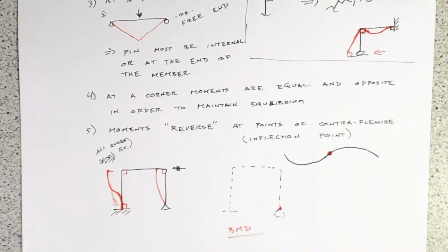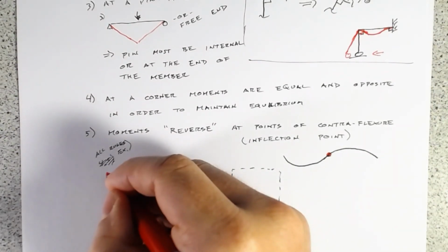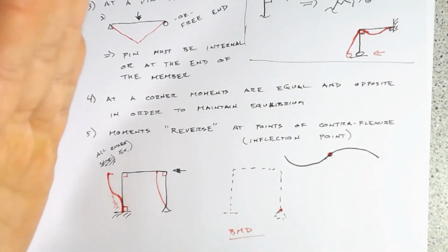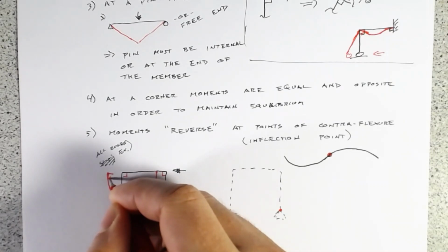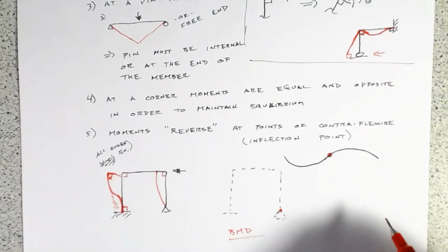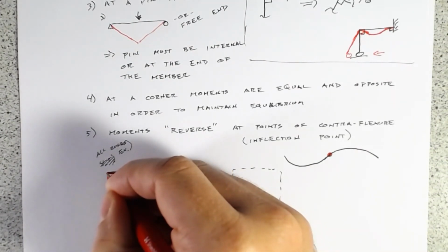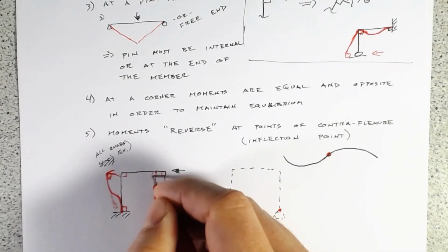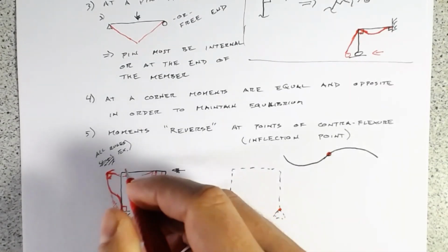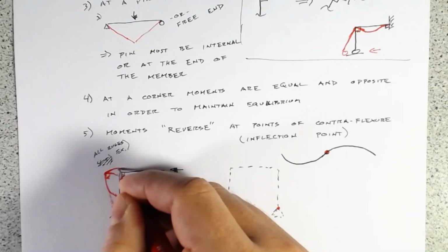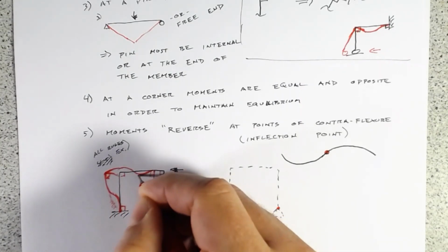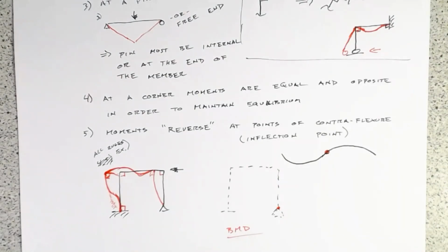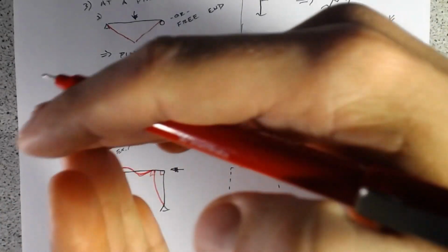All right, so now the next rule is, we've got some curvature. It's tilting this way over here, but that has to stay at 90 degrees. So that means that our column's going to be pointing kind of like that. And this has to stay at 90 degrees. It's going to point like that. And that's our deflected shape. So yeah, that's not quite there, but we've got that.